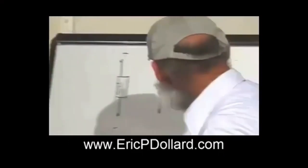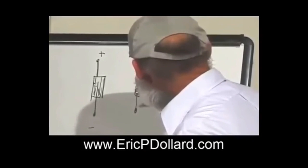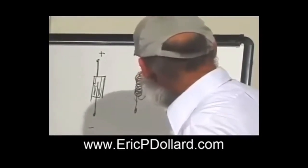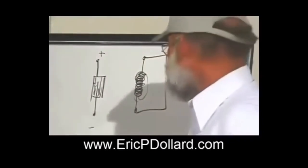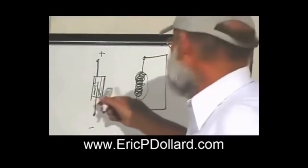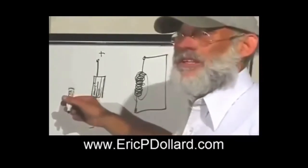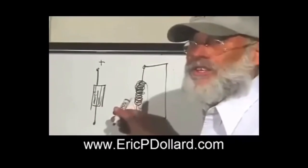Now if I have current flowing through this device, it has a magnetic field. In order to have a current flowing through, of course, it has to be short-circuited. If I'm going to maintain the electrostatic energy so it doesn't go away, this has to be open-circuited. If I'm going to maintain the magnetic energy, it has to be short-circuited.